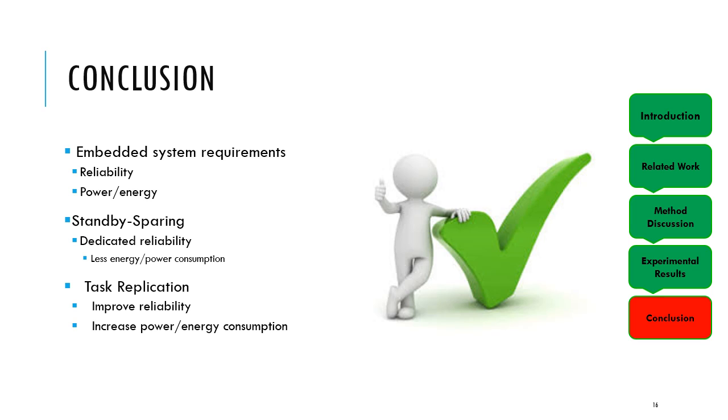Our evaluations showed that if the reliability target is given, standby sparing can achieve low power and energy consumption. But if we want to increase reliability, we should note that task replication will increase power and energy, and the frequency level of course plays a significant role in management of power and energy.